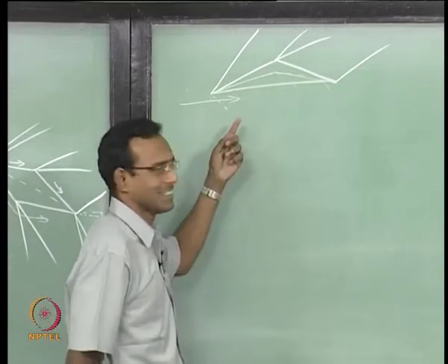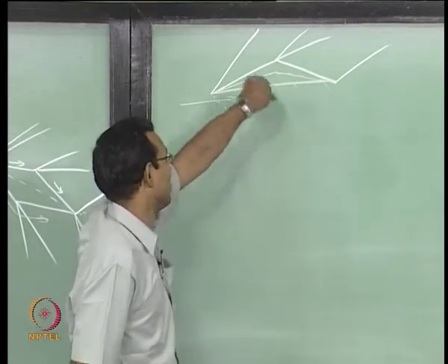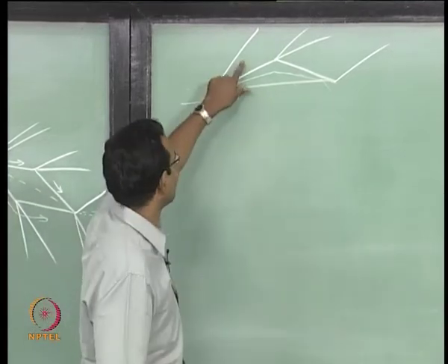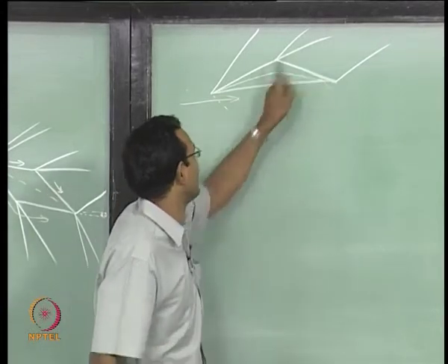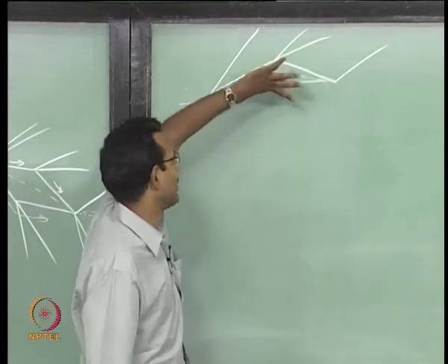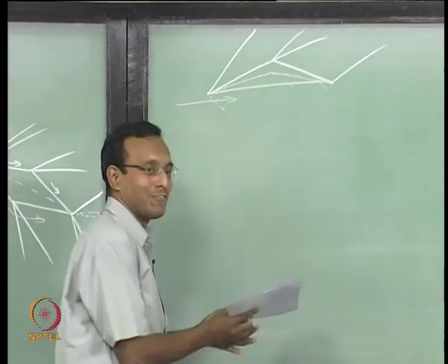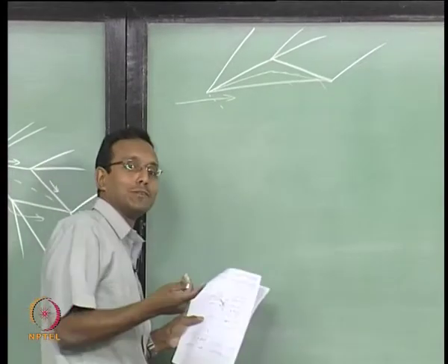That is not the only thing this will have. This will have a huge torque downward. Okay, it will have a negative torque on it. It will have a moment on the airfoil, because this pressure is high, this is some middle, this is low. So this force will be like this, this force will be like this. Overall, it is going to have a torque around the center. It is not a good airfoil to use in any aircraft, but this kind of flow field you have to get used to solving.